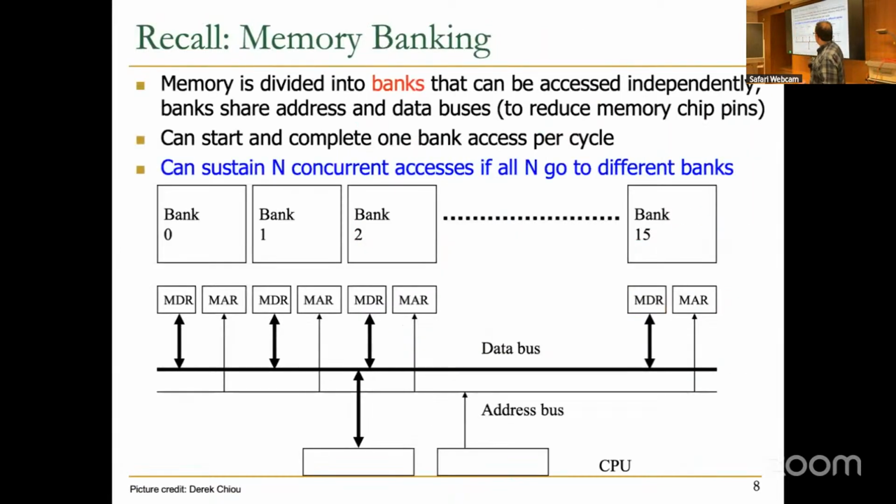And in order to make them effective, you really need to feed the pipeline with data. That's why these array processors and vector processors rely on highly parallel memory and memory banking. Basically, you need quite a lot of bandwidth in order to access your memory. And that's not only for your off-chip memory access, you also need high bandwidth for your register file when you want to access a register and bring it to your pipeline.